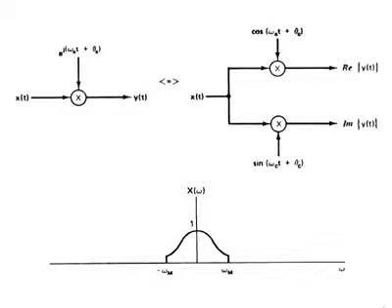And so in a practical system, modulation with a complex exponential carrier would be accomplished with sinusoidal carriers that are in quadrature, as it's referred to, or equivalently 90 degrees out of phase.